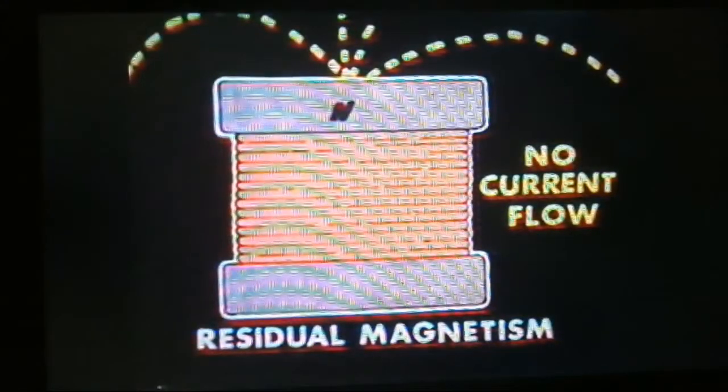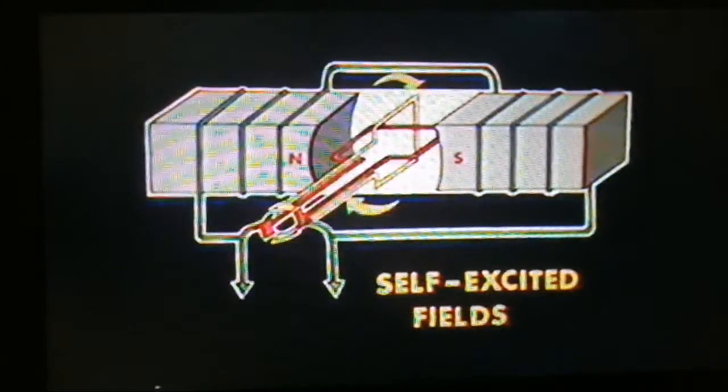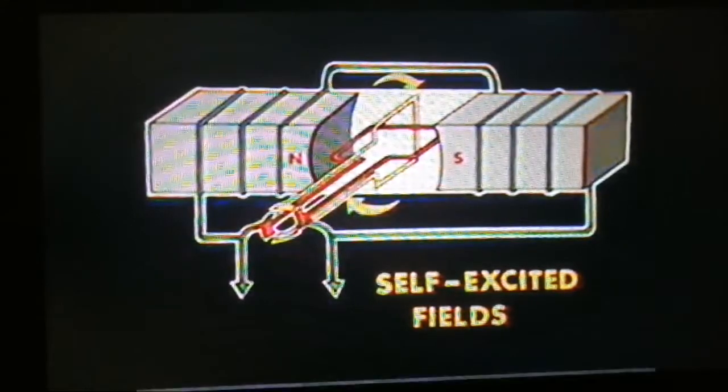Eventually, however, the changes in excitation currents have less and less effect on the power produced by the rotor windings, since flux lines reach a point of saturation. At this point, generator voltage levels off. Strong electromagnetic forces affect the soft iron within the field pole piece, and it usually retains some magnetism even when no current flows. In a self-excited generator, this residual magnetism is enough to create a small voltage when the rotor coils move through these flux lines. If the voltage generated is initially enough to overcome resistance in the field, current flow will increase the magnetism. This starts the rapidly rising progression until the poles are again saturated.